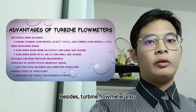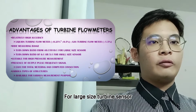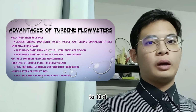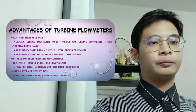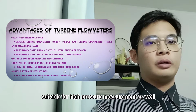Besides, the turbine flow meter also has a wide measuring range. For a large size turbine sensor, the turn-down ratio can be from 40:1 to 10:1, and for a small size sensor tube, it can be 6:1 or 5:1. The turbine flow meter is suitable for high pressure measurement as well.